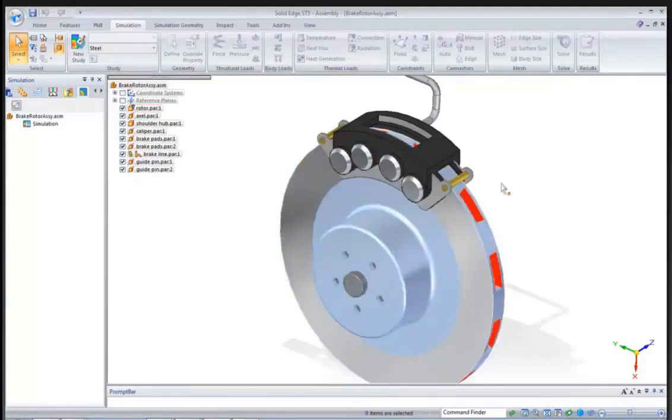So I use that potential energy, which is just the weight times the height of the hill, weight of my truck times the height of the hill, and I have to absorb 85% of that with my brakes. Because you've got losses with friction and whatnot, 85% of that energy has to be absorbed by the brakes. I've got 4 brakes, so I divide that by 4. I've got a spreadsheet, I calculate that out, I get about 2,400 watts. So this brake has to absorb 2,400 watts of energy, and I want to see how hot it's going to get.